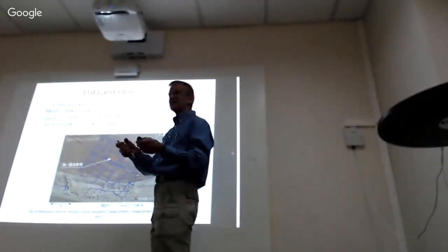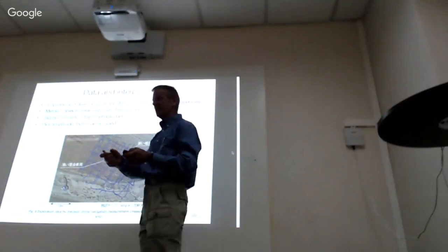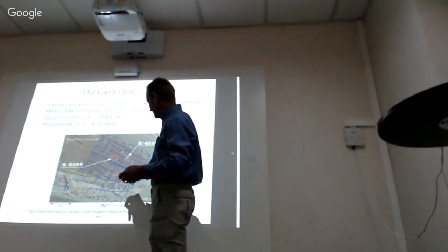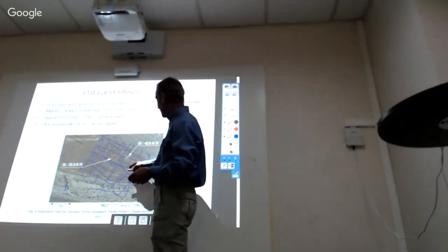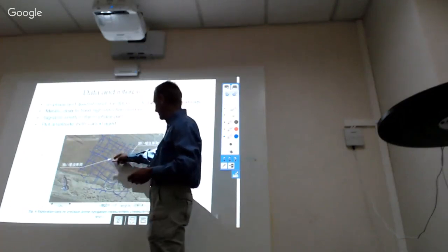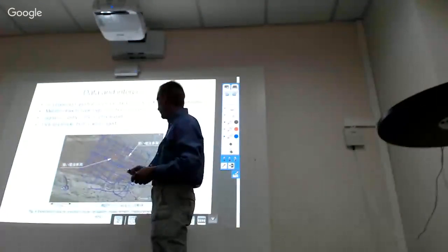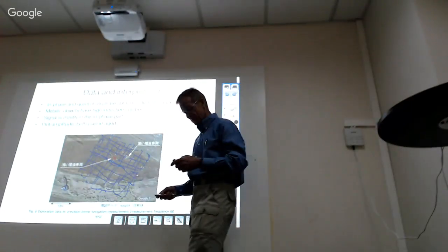That's why these kids are probably better geophysics guys. You know, they've grown up. They've got 2 thumbs on a little joystick. Anyway, this is the path of the drone, and then it's plotted. What we've got here is the signal color coded. And so here is the 1 car at 1.5 meters depth, and here it is at 3.